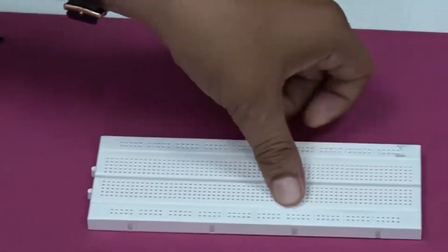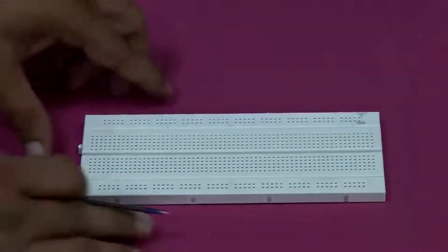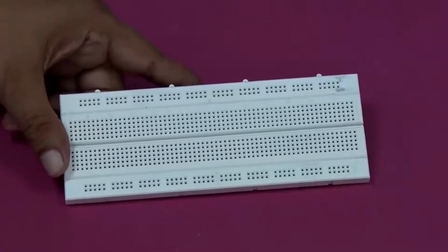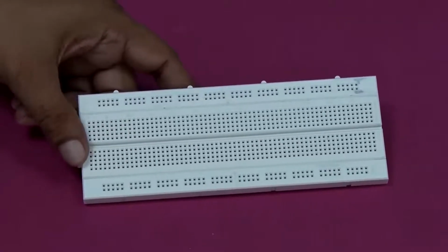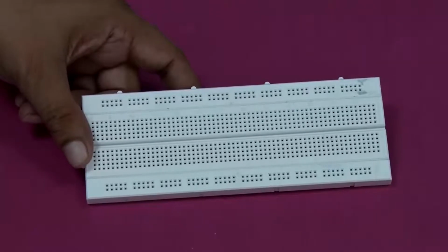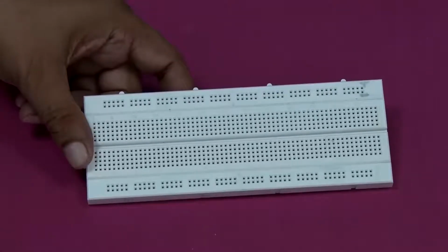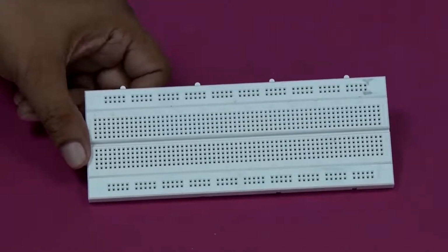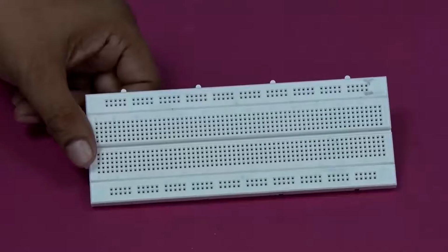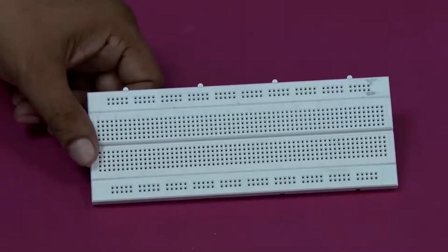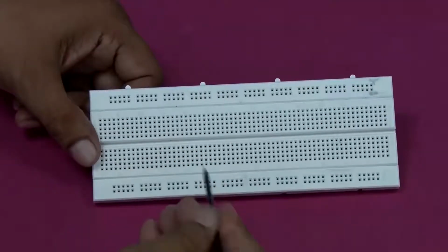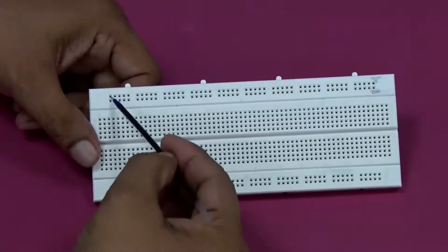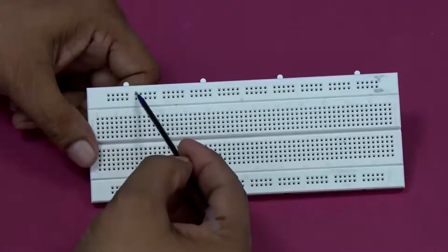So now Ranjit has to help me. As I said, you have all the negatives of the battery, the black terminals of the multimeters, and the emitter, all connected to the zero potential line. They have to be connected to each other, which we will be calling zero potential. So on this breadboard, I will be using this line here for that zero potential. They are all connected to each other.